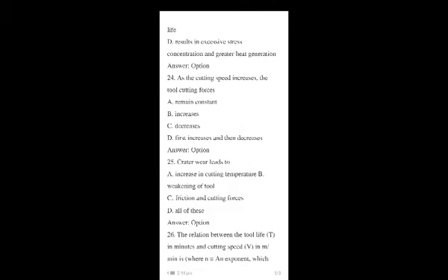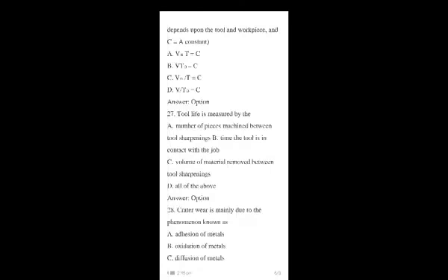Okay, so 26th question, the relation between the tool life in minutes and cutting speed in meter per minute depends upon the tool and workpiece. Okay, so the correct answer is option B, Vt raised to n equal to C. The tool life is measured by all these factors.